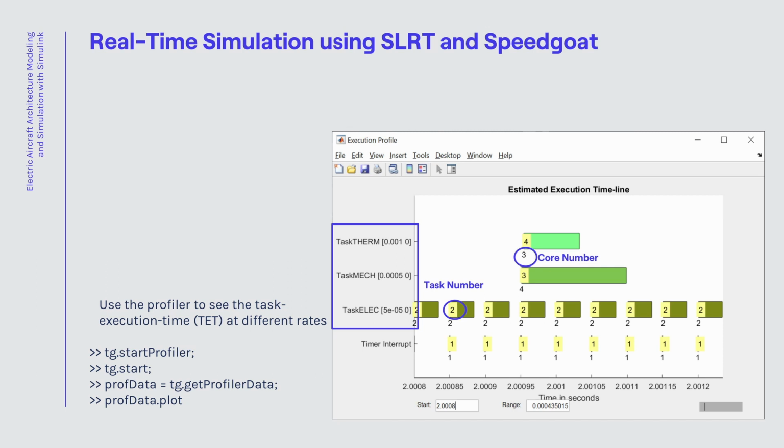So to re-emphasize with those sample times that we are seeing here, the task execution times tell us that we would be unable to simulate the full system in real time if we didn't split the sample times across different model sections, and we were unable to use lower sample rates for the thermal system and Brayton cycle gas turbines. With explicit partitioning, we have further control of using computational resources on the real-time system. And as model complexity develops, we may consider partitioning the model at different locations and including more than one sample time per core. These choices will, of course, be system-specific.